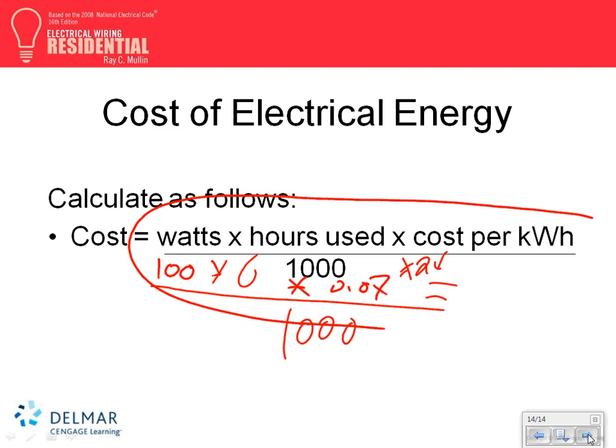So you have a 20 amp going here. If these are the same size, same type, that 20 amp right here is going through here and splits right here. So you have 10 and 10. Absolutely, you have 10 amp here and 10 amp here. They're parallel. They go back to the source because they're also bonded here. So now it's working as one conductor, they're tied together.